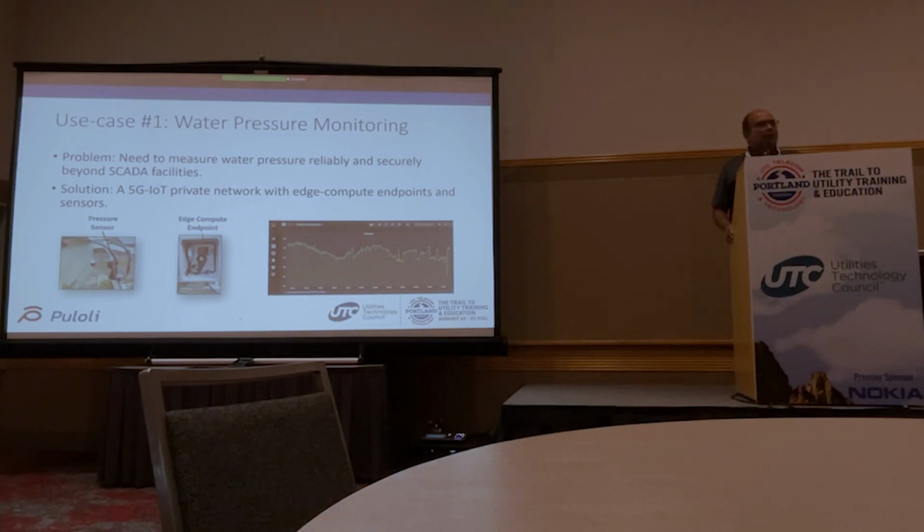So I think migration towards, this is strictly my personal opinion, there are a couple of guys in the audience who really know better than I do. Come by our booth. They'll be happy to give you a lot more insight. But my high-level take on it is that if you go towards an I2C kind of implementation, that becomes very possible. That will be the best guideline I can give, moving away from current loop where possible, as long as the environmental and regulatory framework allows the utility to move away from that sensor to an I2C sensor. I think that will be a first step.